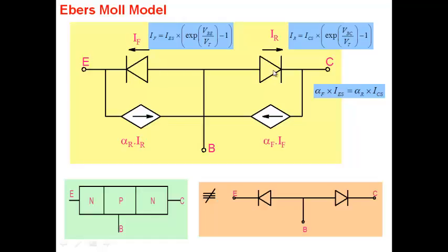What is the most important thing in a bipolar transistor? The two diodes that you see here is fine. Whatever is the current flowing here, a part of it flows here also. This linking of the two junctions. Whatever is IR here, something flows here. The linking of the two junctions. That's the bipolar action. That's where all the transistor action is. It's not simply two diodes, that is all. Okay, so let's stop.